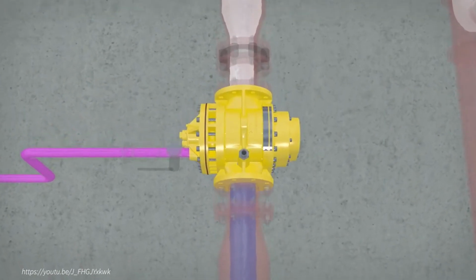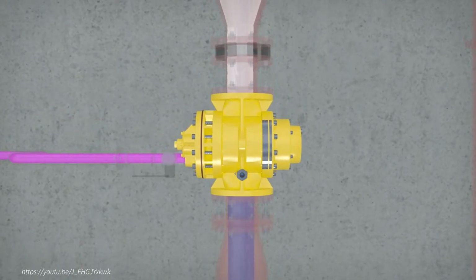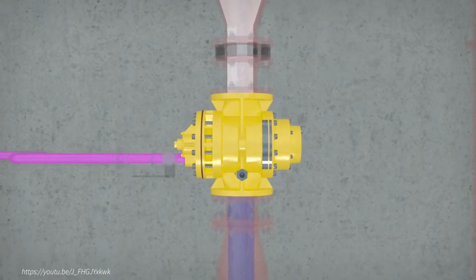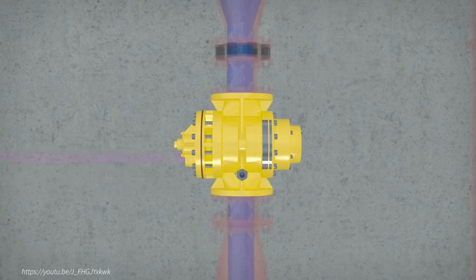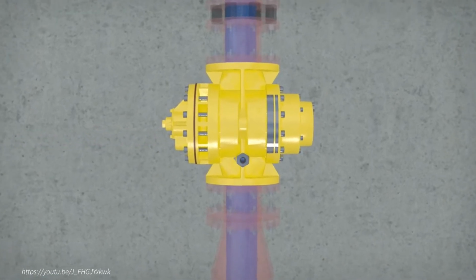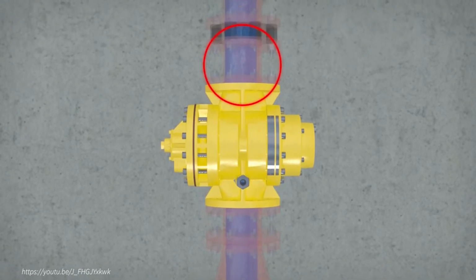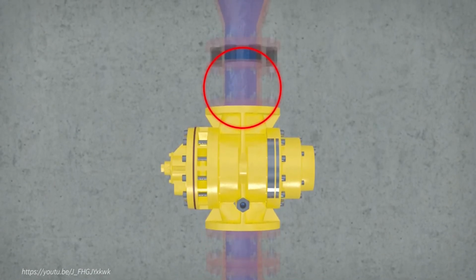A 3-way valve is fitted in the foam suction piping. In normal use, this allows the foam suction to take foam from the tank. However, it serves a dual purpose, as it can be set to isolate the tank and allow water to enter from the inlet of the Turbinator, thereby allowing either a flushing action or to use water for testing purposes instead of foam.